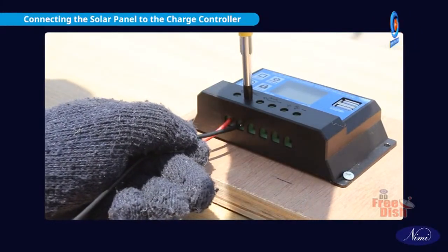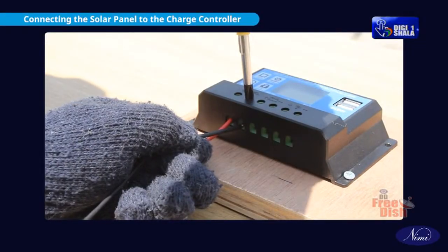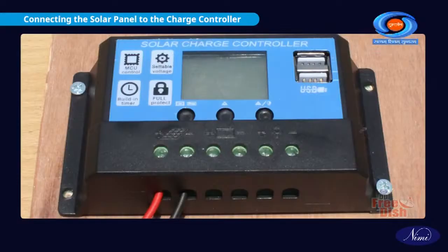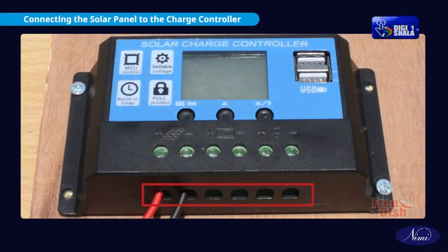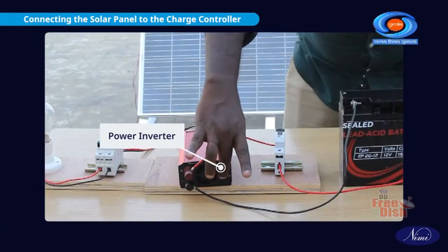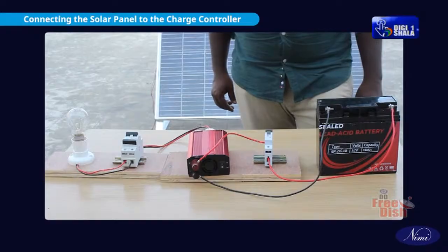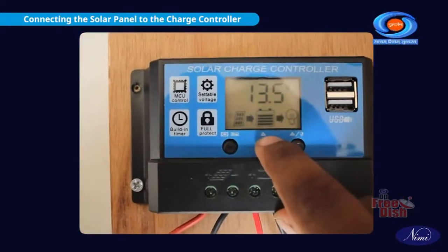Ensure that the connections are secure and tight to prevent them from coming loose over time. Some charge controllers have screw terminals or other connectors to secure the wires in place. Now, switch on the DC circuit breaker and inverter. Ensure the load connected to the inverter is working and monitor the solar panel and battery voltage on the charge controller display.